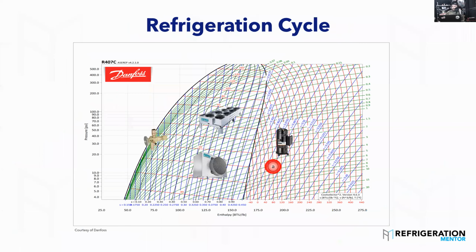But anyway, I did a TikTok just explaining the filter dryer thing and checking across it, and somebody sent me a video of an air conditioning system where the liquid line was actually frosted after the liquid line filter dryer, because it was so plugged. Like Trevor was saying, it was creating a metering device, and it was frosting on the outlet all the way up to the metering device. It was crazy.